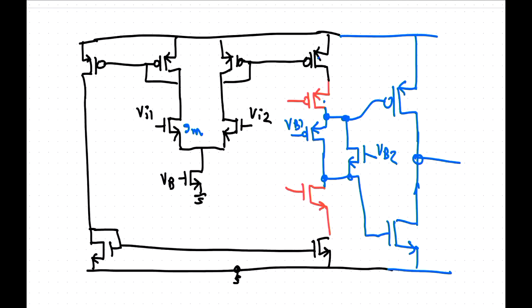That's going to drag this node voltage up here. So if you push current into this node, both of these nodes are going to go together, and they're going to be pushed up very high. So that means it can go pretty close to the power, really can actually reach the power supply. So you can turn this one here off and have a very large gate source voltage on the N transistor there, which means that you can draw a lot of current in there. You can easily drive a resistive load now. So this is a good low output impedance output stage. That is rail to rail.